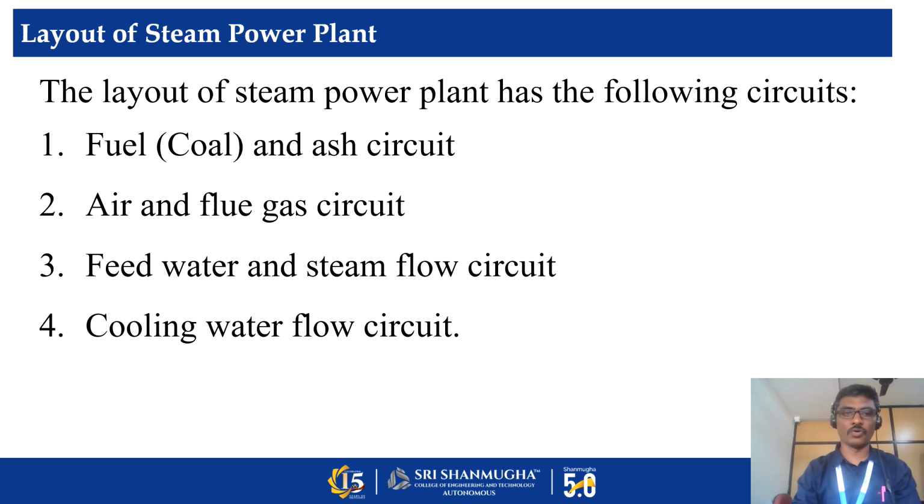Layout of steam power plant. The entire layout is classified into four circuits: fuel and ash circuit, air and flue gas circuit, feed water and steam flow circuit, and cooling water flow circuit.